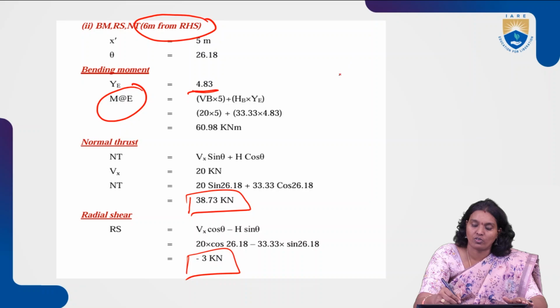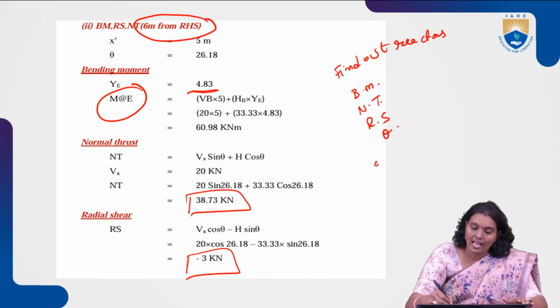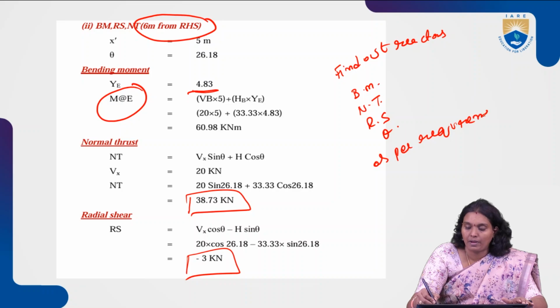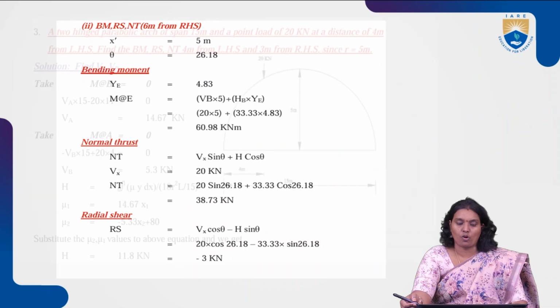The first step, find out the reactions. All the reactions. Find out the bending moment and normal thrust and radial shear and also the theta. As per the requirement, calculate the parameters. These are the basic steps which are involved in this kind of problems.